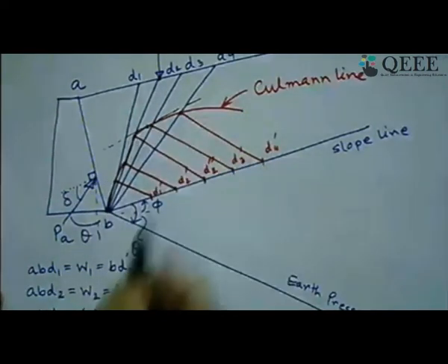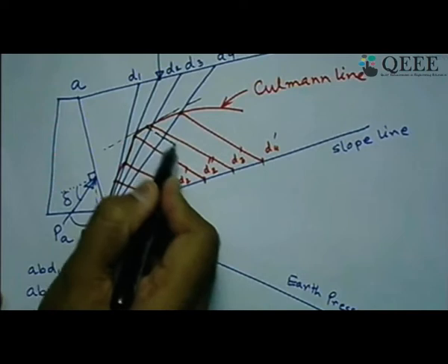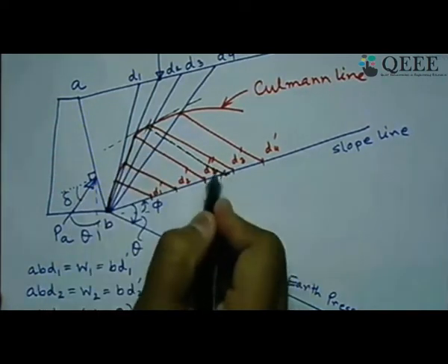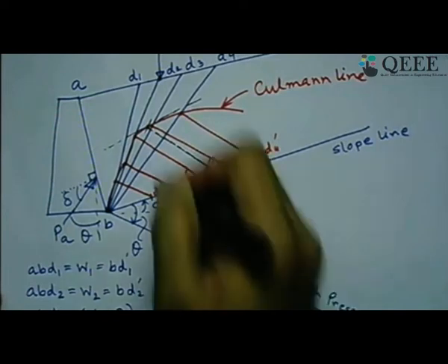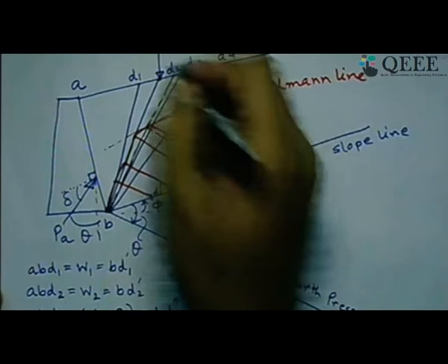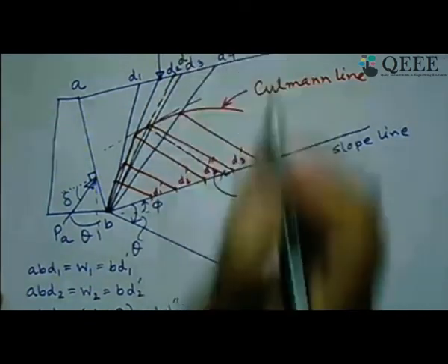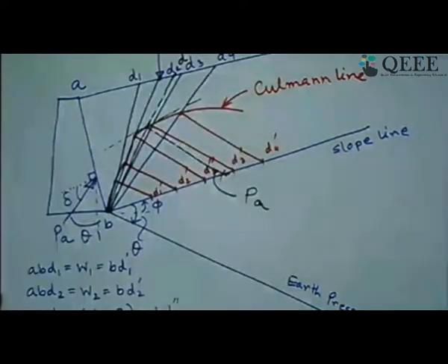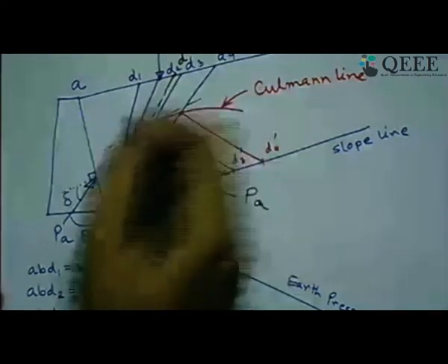Let us say this is the point. Then you join this to this, and that gives you the design value of PA, and that point you should join here with the heel. That gives you the failure point of D. So this is the value of PA, which includes the value of Q, and this is the failure plane by considering the line load.